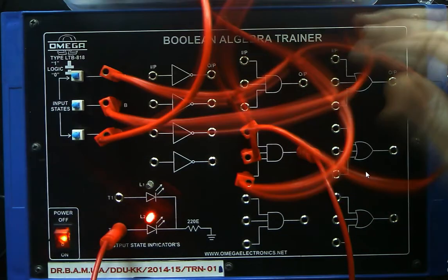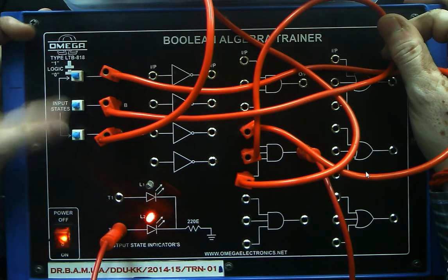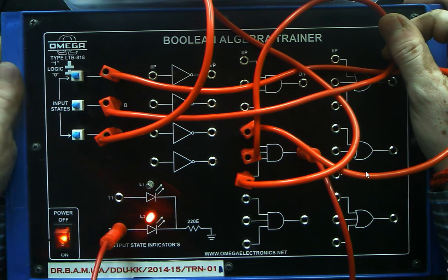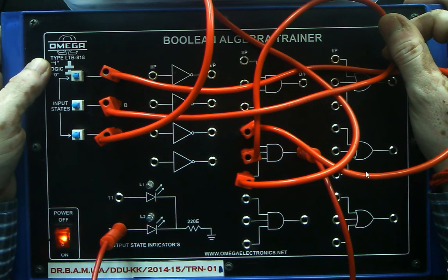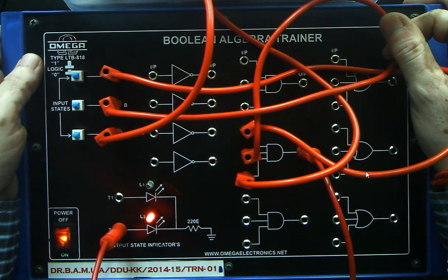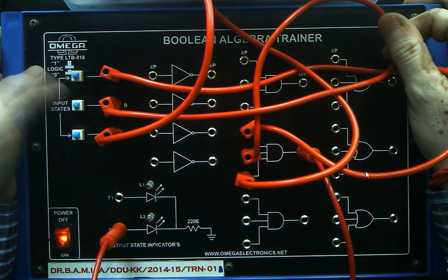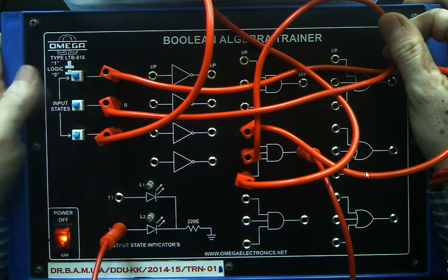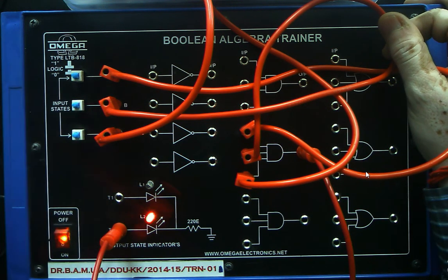I understand that this will be a problem for your visual understanding. All these three switches are in their high state. Therefore, the output is high. Now, if I make any of them low, you can see the output becomes low. This is very obvious because an AND gate requires all of the inputs to remain in high state in order to have a high output. Okay, so this we can verify within just our Tinkercad.